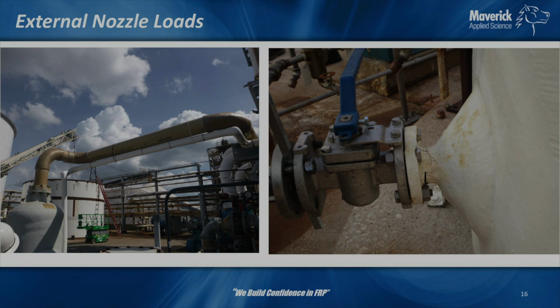So here's another example. You've got a pretty small vessel here. Maybe this is an 8 or 10-inch pipe coming up. So you've got this long span coming in. It's probably supported way back behind here. So all that's in offsets. Sometimes you can get away with it where if you're coming straight in and dropping right in, you're minimizing moments. But when you start putting offsets, it's just like a doubler. So you've got twice the moments going in there, and then that didn't challenge enough, so we decided we'd strap on a whole other pipe and add these other fancy pipe supports here. Let's complicate it even more.